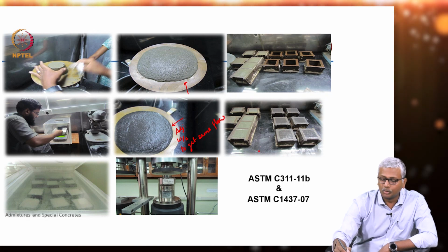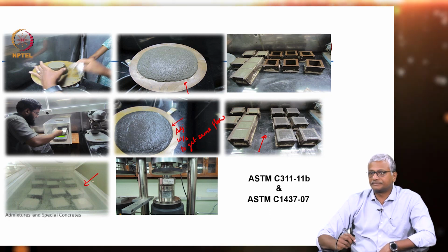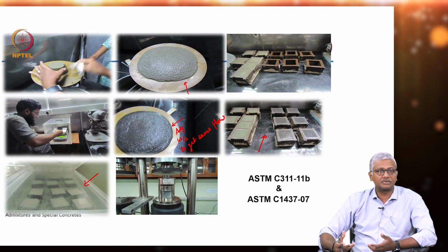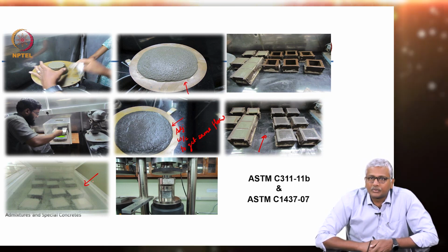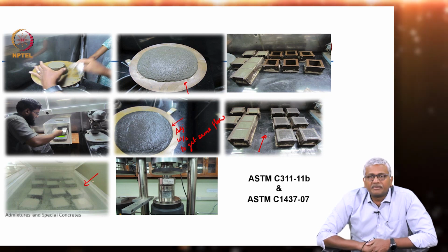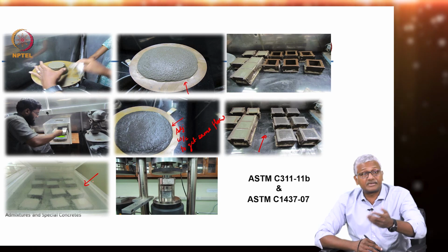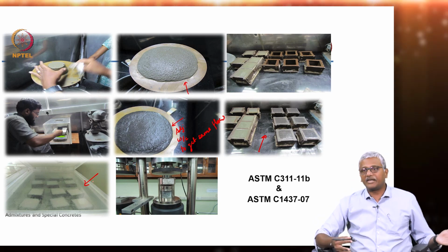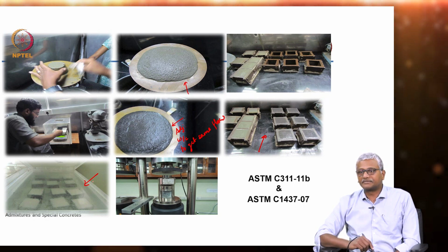And you prepare your cubes, store the cubes in saturated lime solution. Okay. You can see the cloudy white solution, basically it is saturated lime solution. Okay. Any idea why we want to store it in saturated lime solution? What will happen if I store cement based materials in plain water like it is done on site, right? On site we have a curing tank, we have plain water inside, we just dump the cubes inside that. What is going to happen?